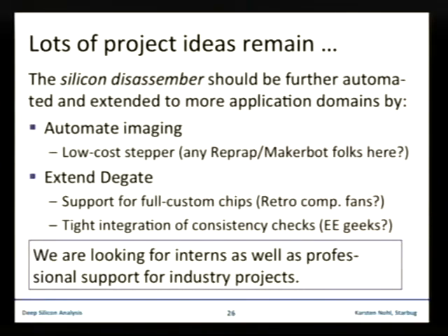Take an old hard drive, then you have a linear drive, and if you apply DC to the coil, it moves in one or the other direction. Then you should get some position, and so you can make a mirror and maybe some CCD scanner line, and then you know where it's moving. So this would be one construction. You can move a lever from left to right, and you make this two times, and so you have an XY drive. It has cylindrical coordinates, so you have to do a little bit of calculus, but it's a cheap solution.